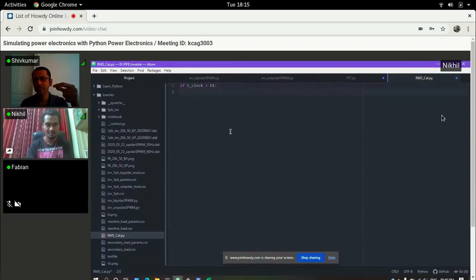So therefore, you set up what is called an interrupt. If you use DSP or something, you set up an interrupt. So every time the timer goes to 0, it issues an interrupt. Then you run an interrupt service routine. Okay. So this is like simulating an interrupt service routine. Then after this, always remember, do not forget to increment your timer.